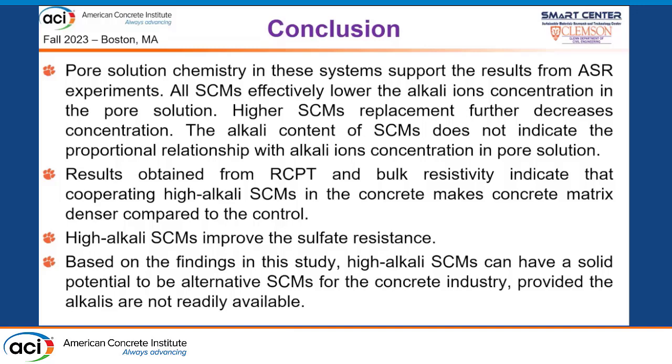Results from the RCPT and bulk resistivity indicate that incorporating high alkali SCM makes the concrete matrix denser compared to the control, and this material also increases the resistivity of the concrete.